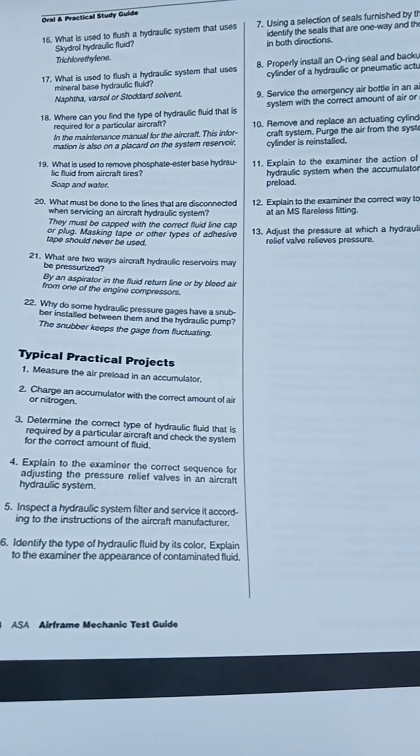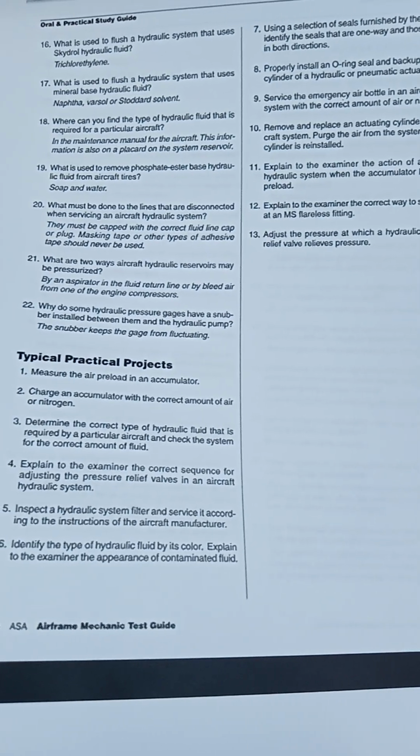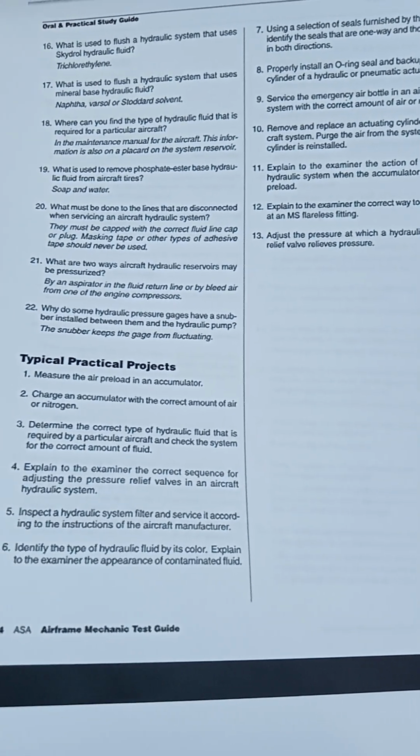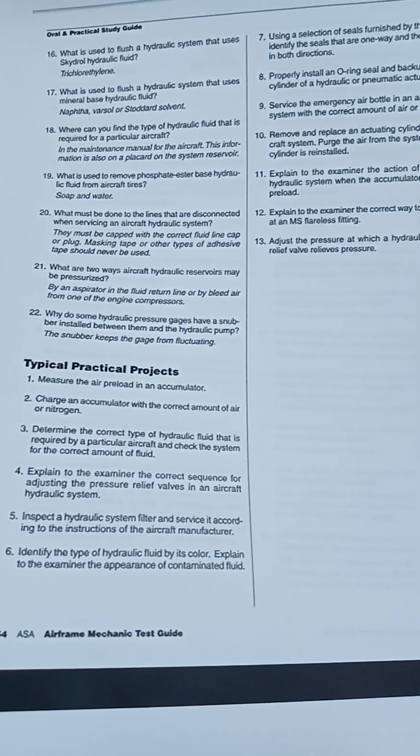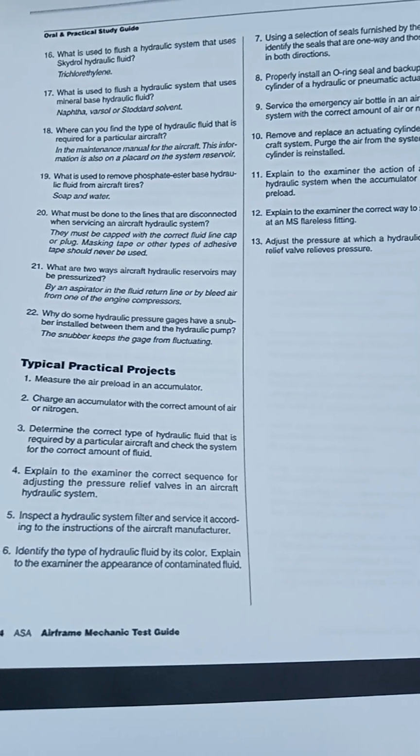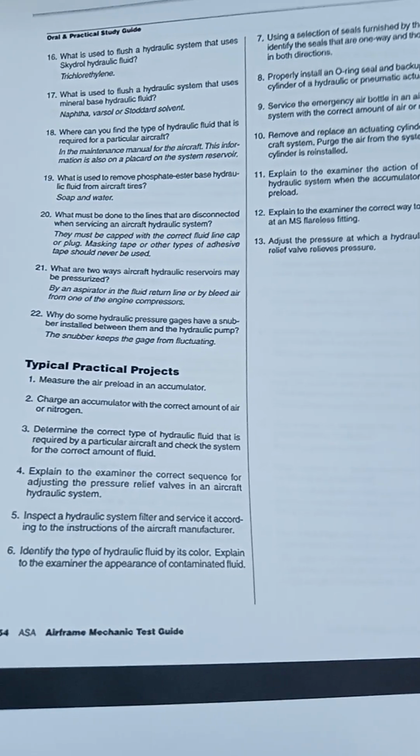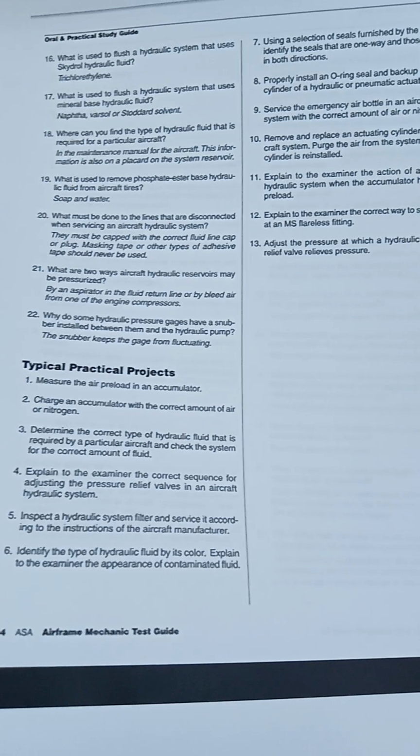What must be done to lines that are disconnected when servicing an aircraft hydraulic system? They must be capped with the correct fluid line cap or plug. Masking tape or other types of adhesive tape should never be used. What are two ways aircraft hydraulic reservoirs may be pressurized?